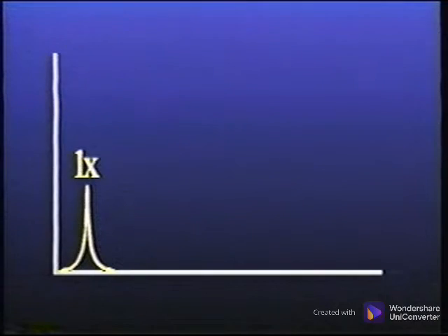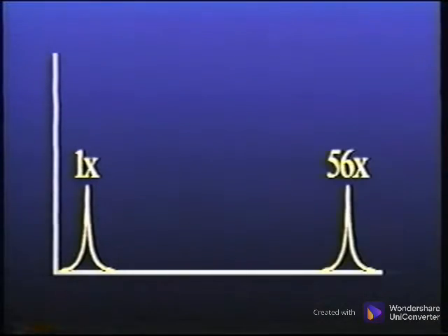In spectral data, we expect to see peaks of some amplitude at 1 times turning speed due to unbalance, misalignment, or some amount of looseness. On gearboxes, we expect to see a peak at gear mesh frequency, which is the number of teeth times the turning speed of the shaft. On pumps or fans, we expect to see peaks related to vane pass or blade pass. The presence of these peaks does not necessarily indicate a problem or fault.